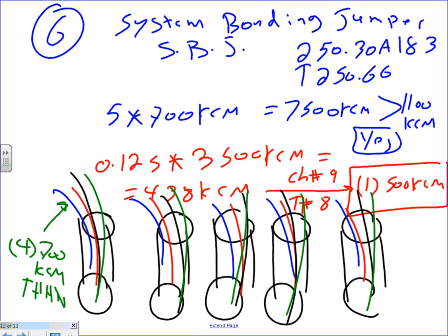Oh, I got it. 700 will give me 3.5 for 4 conductors. So that conduit here is going to be 3.5 EMT. Can I put rigid? Yeah, bring it on. Why EMT? Because if I'm THHN, I'm indoor. If I'm indoor, most likely I'm EMT.